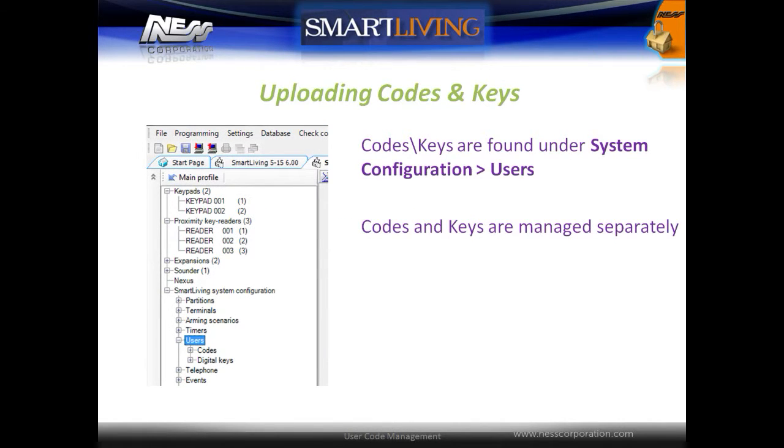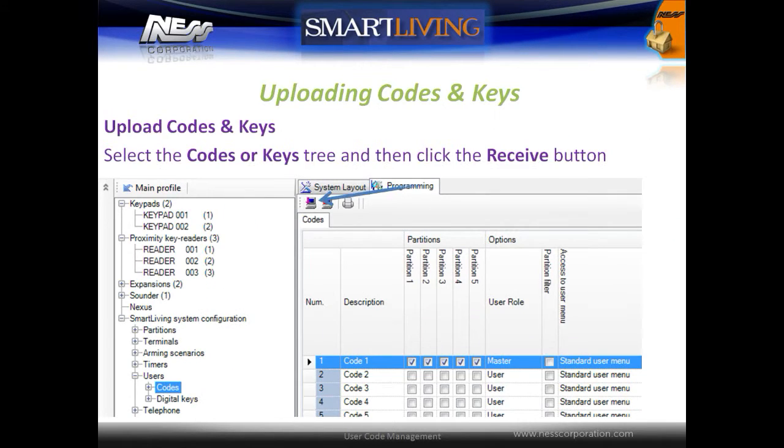Codes and keys are found under the User menu under System Configuration. User codes and digital keys are configured and managed separately. Select codes or digital keys and then click the Receive button to upload to the software.